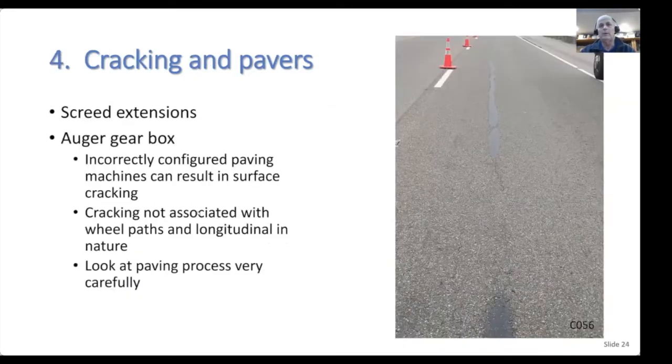When we're looking at pavers, we have to make sure everything is set correctly. You can see some cracks. You know, everyone very quickly wants to associate cracks with the mix performance or something else, but sometimes we'll see cracks associated with pavers, screeds, etc. We have to make sure everything is done very carefully.